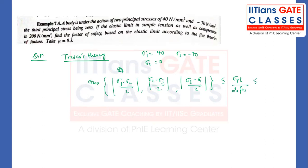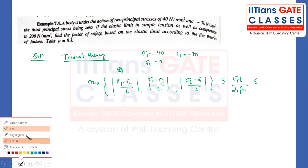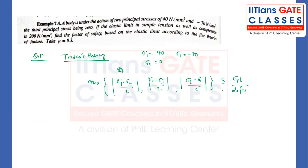Getting my point? That has to be equal to tau yield divided by factor of safety. Tau yield, what we have calculated in a simple tension test, is sigma yield strength divided by 2.